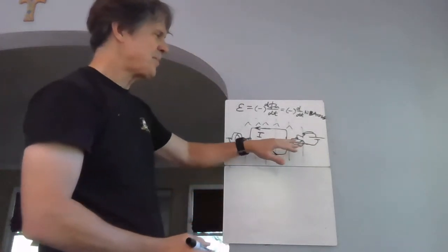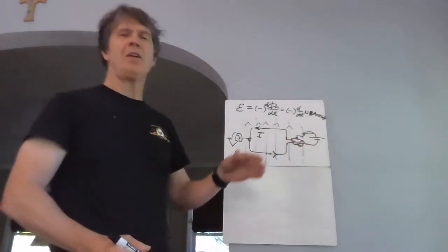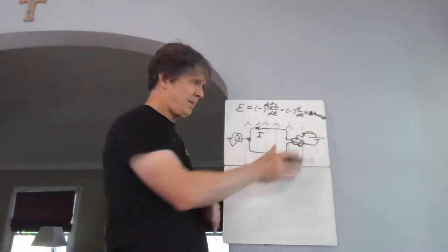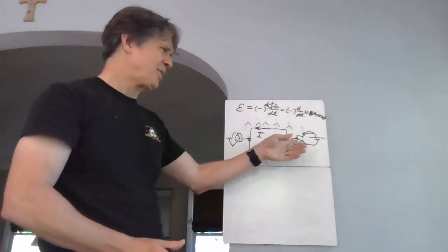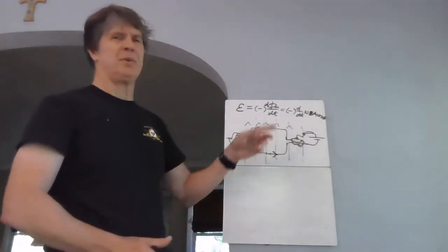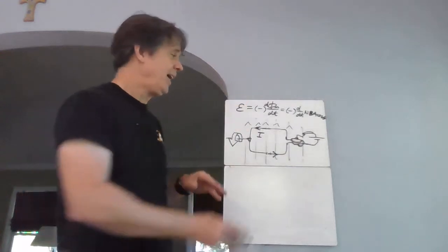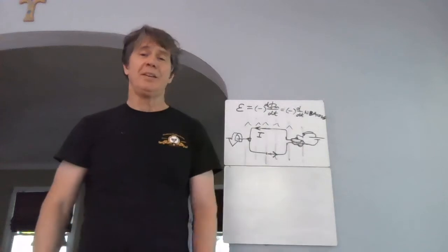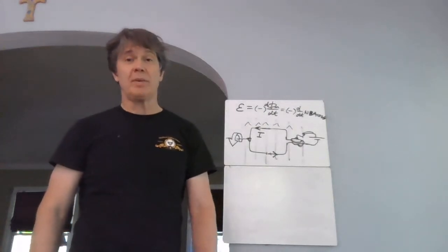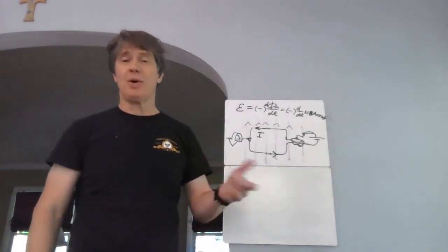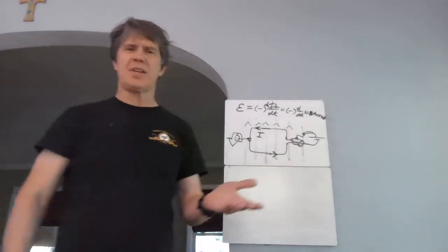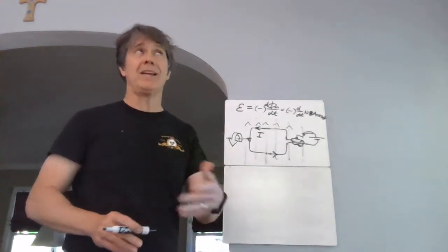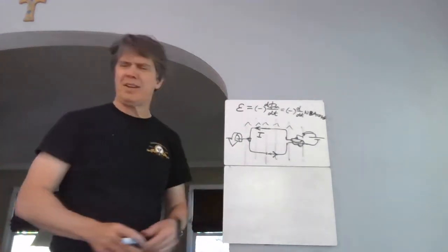But as it spins, it forms an automatic current reversal switch, because when it rotates around to the correct position, the brushes will make contact with the other little metal semi-cylinder, and then you'll reverse the current, and the thing will keep running in the same direction, and that will be, of course, a direct current motor. It'll keep spinning the same way. So, look, motors and generators are really the same thing, using Faraday's law, or using the whole idea of a magnetic force on a current. Okay, enough said about that.